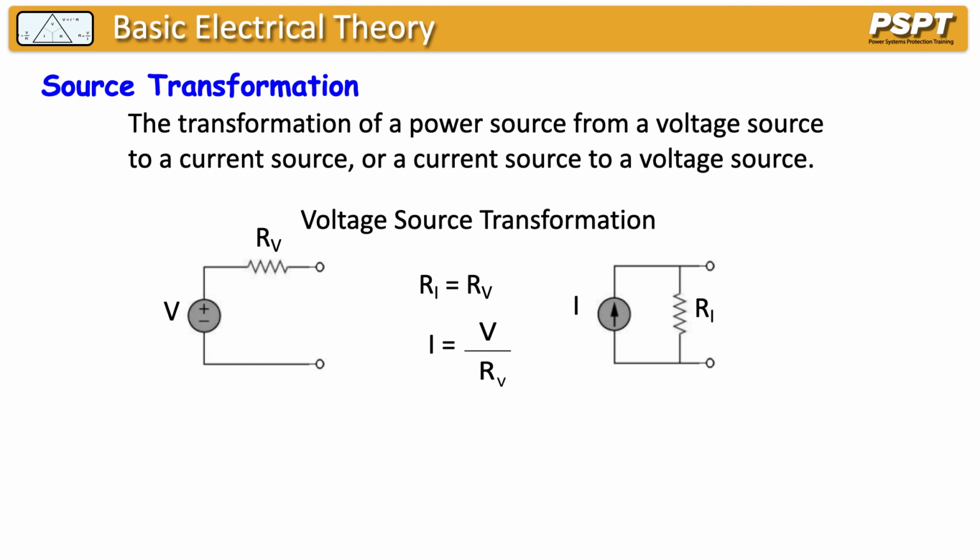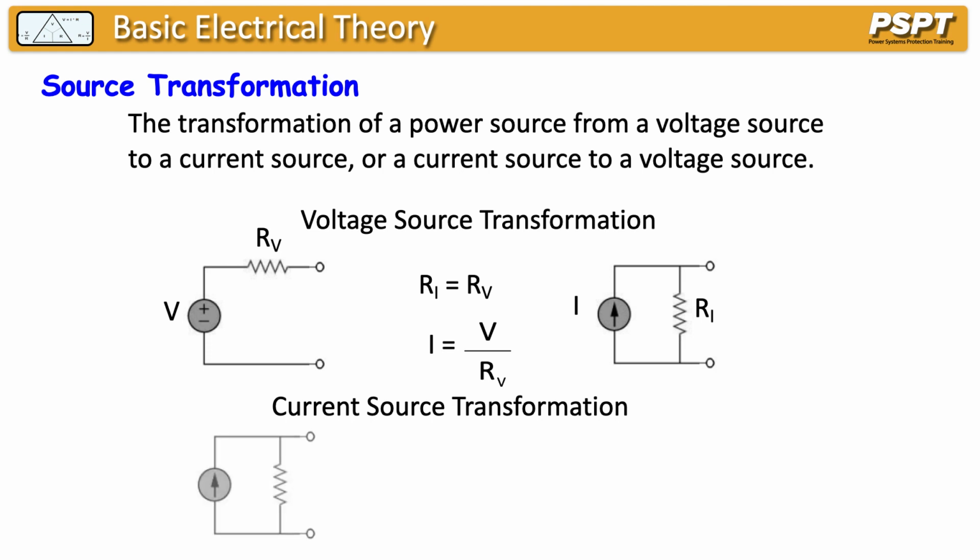If we want to convert a current source into a voltage source, we take the same steps, only this time we're going to be using the Thevenin equivalent circuit. Our current source would look like this. Of course, and we want to end up with a voltage source that would look like this. So we now have to calculate the new source voltage and resistance. We start by using the Thevenin equivalent, replacing the power sources with the required shorts or opens.